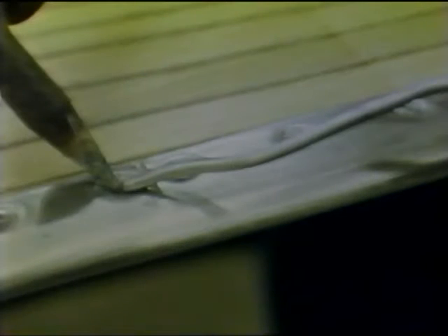Each screw and rivet hole is filled with solder and ground flush by hand. Relief cuts are carefully spaced and calculated to ensure against random cracking due to blade flexing. Depending upon requirements, the propeller is either painted or varnished and finish balance accomplished.